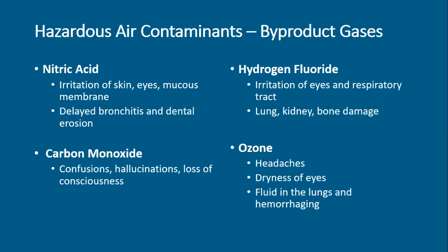The following are general hazards related to exposures to some welding byproducts. Carbon monoxide displaces oxygen in the blood and can lead to a loss of consciousness and suffocation. Early symptoms of carbon monoxide poisoning can include headache, fatigue, dizziness, or nausea. Prolonged exposures to carbon monoxide can worsen these symptoms and increase the likelihood of losing consciousness.